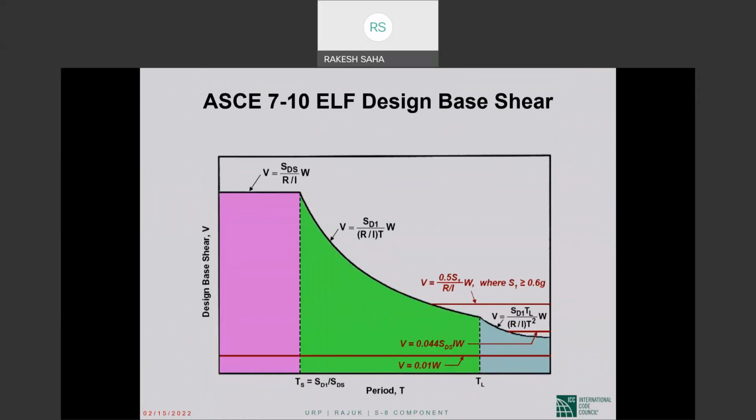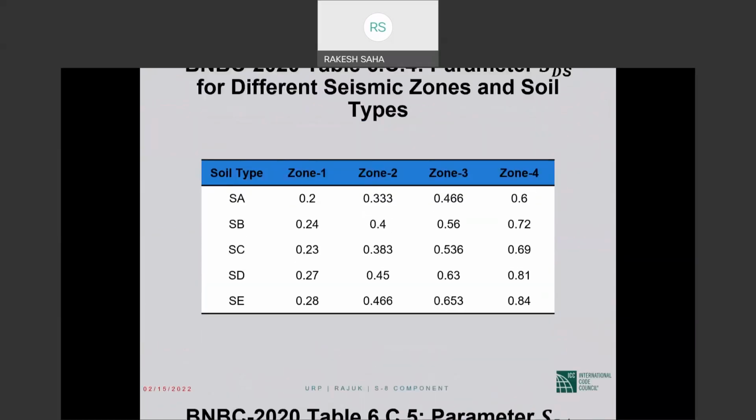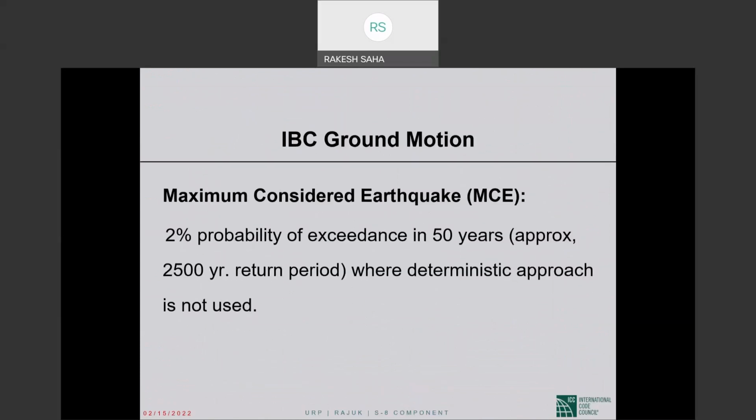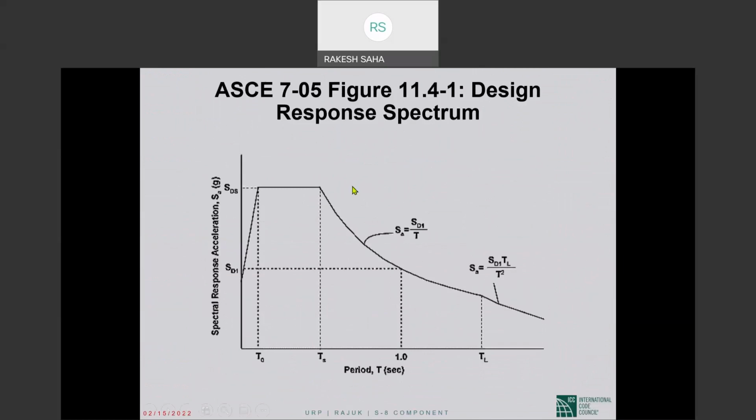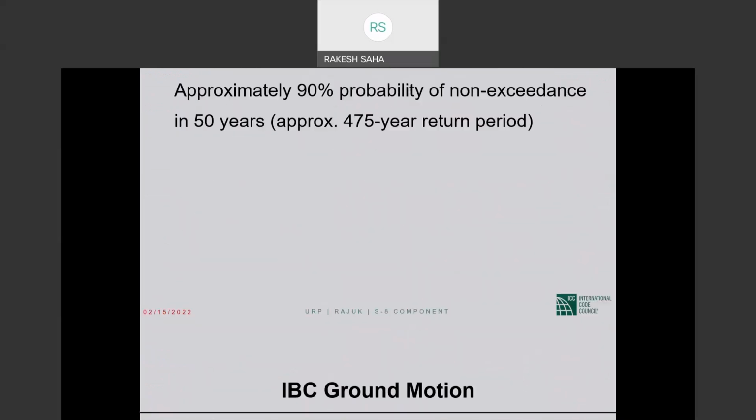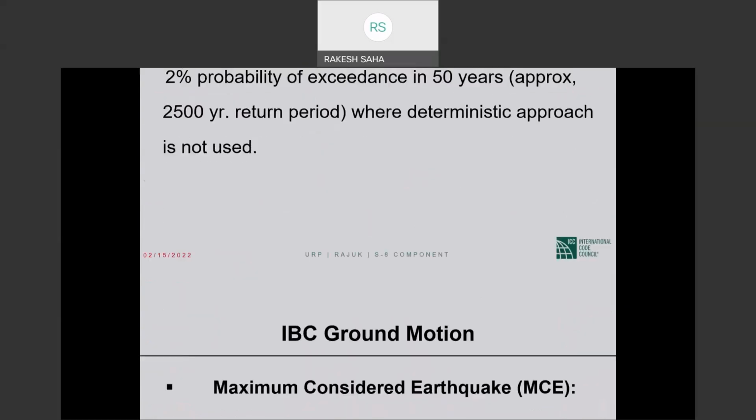With that, you can construct your design spectrum. The other point I made, I don't remember which day now, is that when we do the equivalent lateral force procedure, we modify this spectrum, our elastic design spectrum, in 4 different ways.